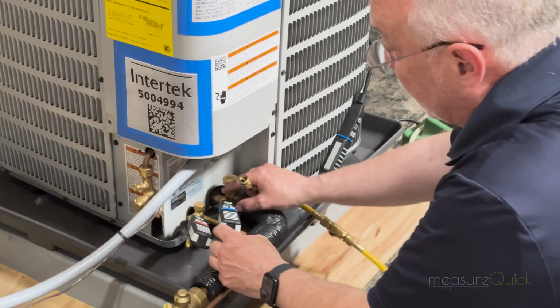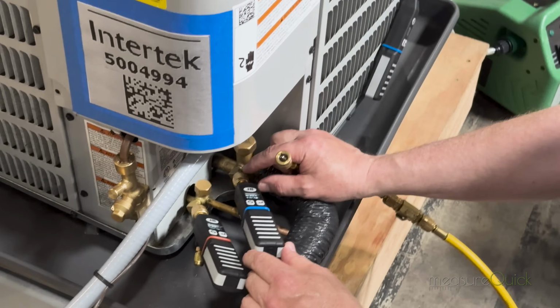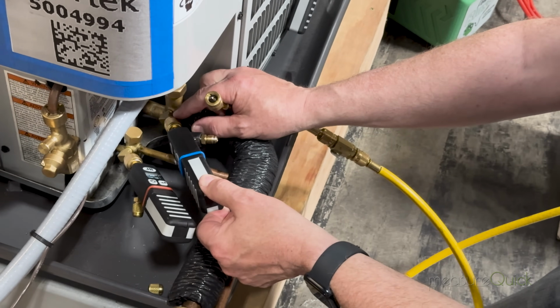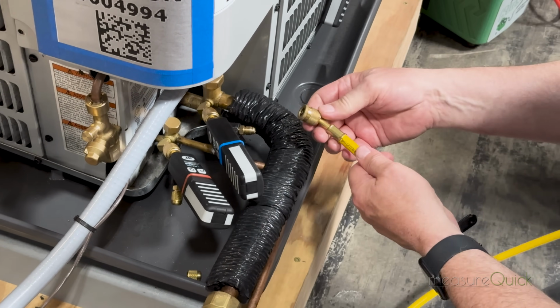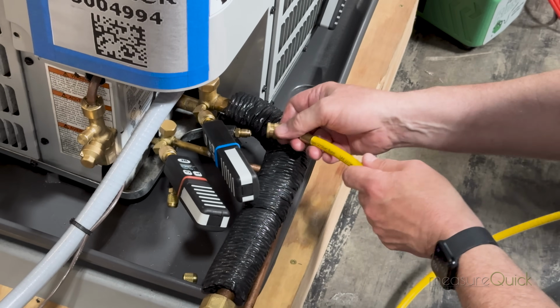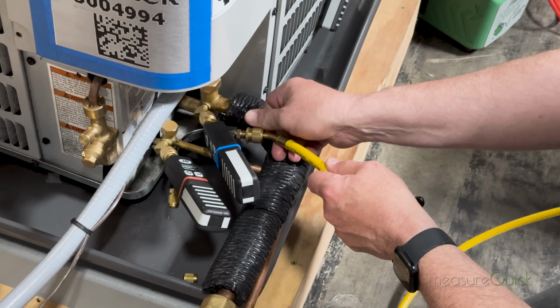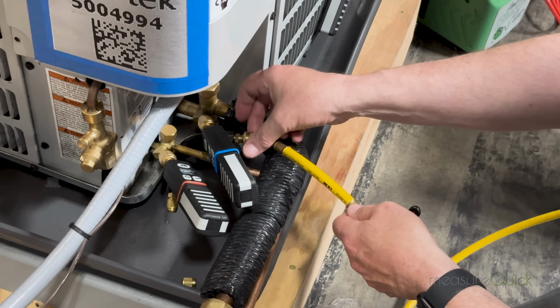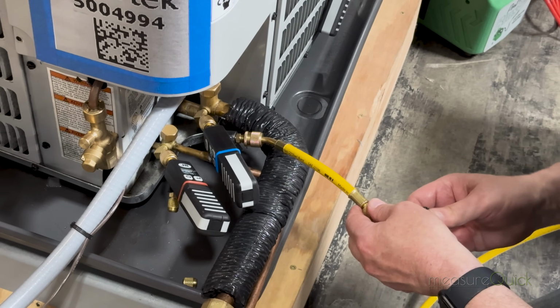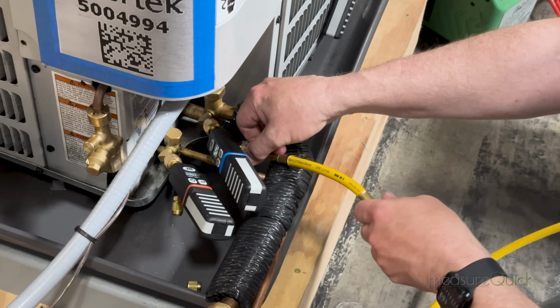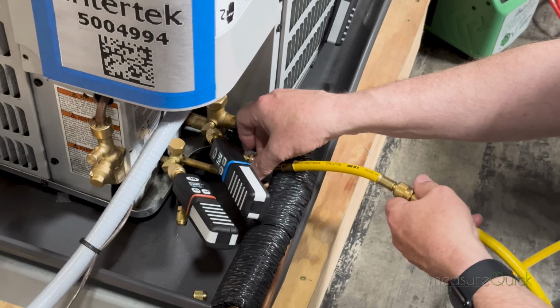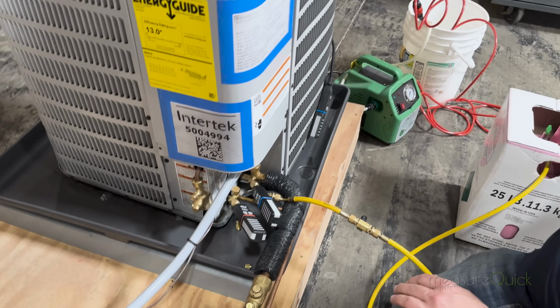And what's nice with these JB probes is that if you turn them to their side, they've got a charging port on the back of them. Because I can actually see the display on my app, I don't have to see the display on the probe. So I'm gonna pull this back, fit it on loose, give it another purge just to purge out any air, and snug this up. So now I've got the refrigerant hose attached and I've got the valve closed for my refrigerant.